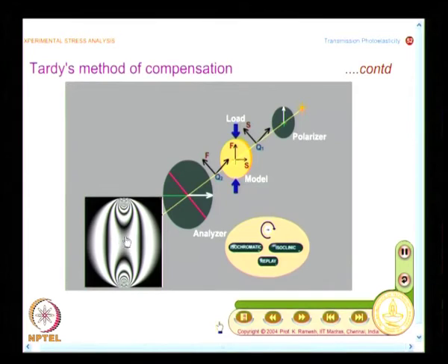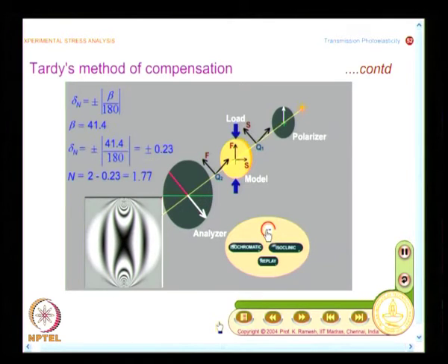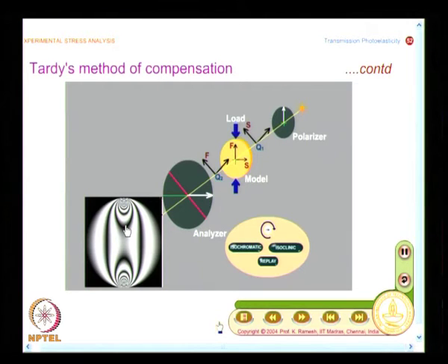So, what we will do is we will rotate it in a clockwise direction. I rotate it in a clockwise direction, what happens? You may not have noted all aspects, it has formed the figure of 8. Now, I will replay this, look at which fringe order has moved and occupied the position. Only now look at which fringe order has moved and occupied the position. So, what we find is the fringe order 2 has moved and occupied this position.